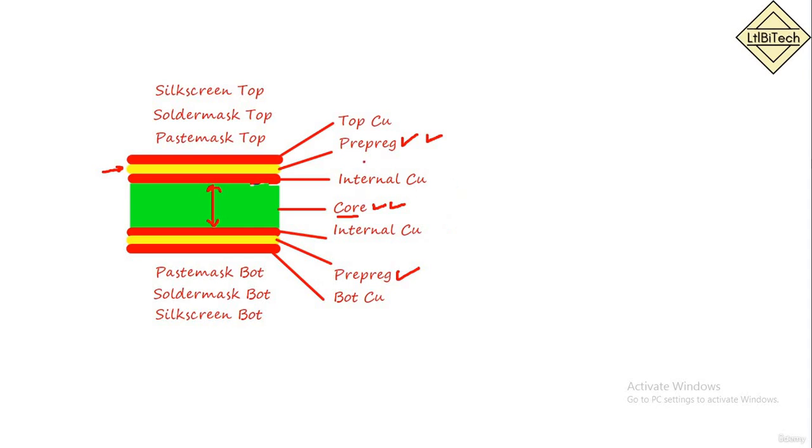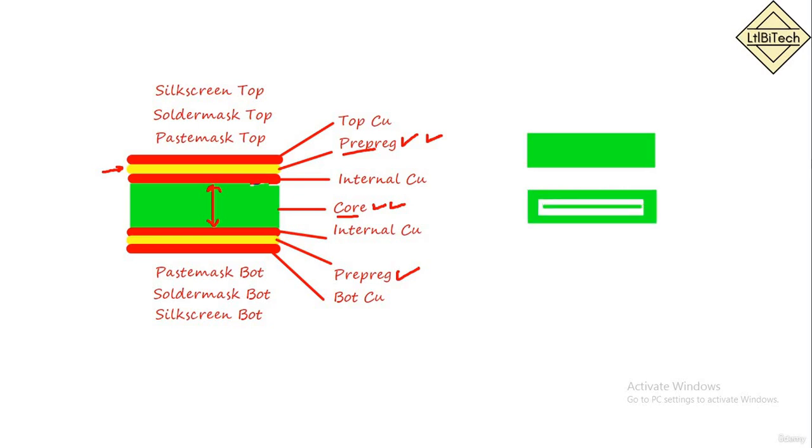So this is used to connect multi-layer PCBs. Whenever we have a multi-layer PCB, we can use this pre-preg component. One more thing about the pre-preg component is that it differs with the structure. Before, we took two coppers with one core material. Now we will take two core materials. This is core 1, and this will be the second core. I'm discussing a 4-layer PCB here. If you have a 4-layer cross section, it would look like this.